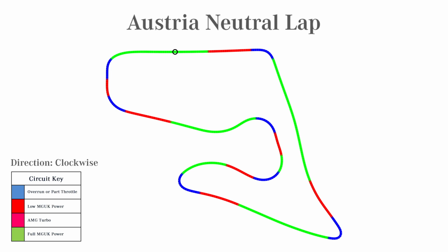So if you can see from the top middle point of the lap, where the little circle shows the start finish, at the end of that straight we would be derating, and then harvesting, and then we go all the way up that long hill. Most of it in the green zone, so most of it with the engine and the MGU-K, but then there is a derate, and then we go around the corner, and then you're into that area again.